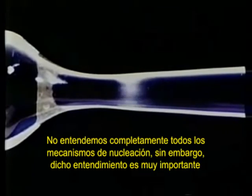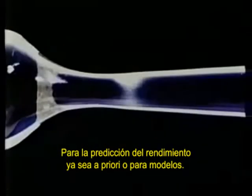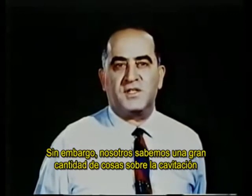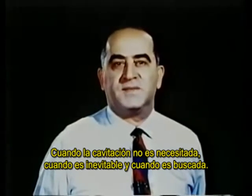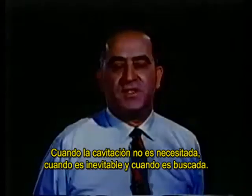We do not fully understand all of the mechanisms of nucleation, and yet such understanding is very important to the prediction of performance either a priori or from models. Many basic aspects still remain to be explained. Nevertheless, we do know a great deal about cavitation, and its effects on performance of machines can be predicted fairly well, when cavitation is unwanted, when it is inevitable, and when it is sought.